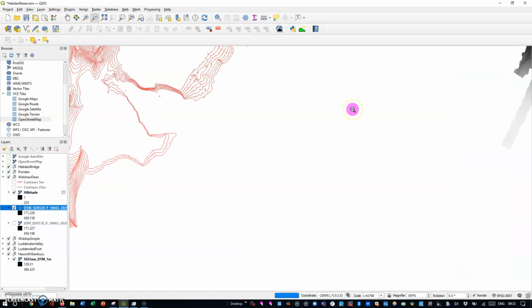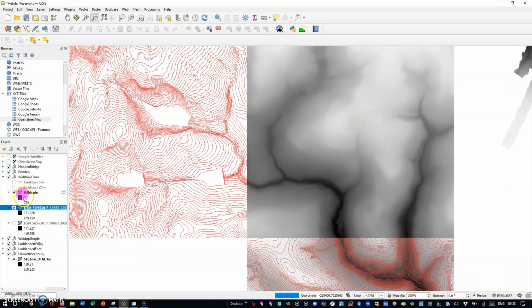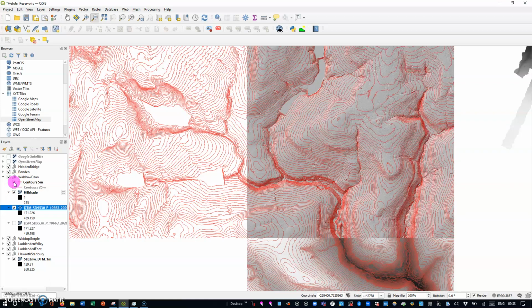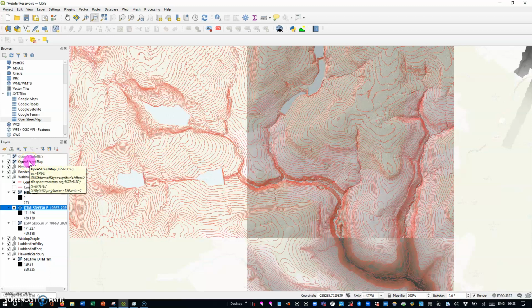We just go in to have a little look, and I've also created some contours at different intervals. They default to 10 meters, and I've made this one 5 meters, and you can see we've got that. I've also got a watered down, transparent 20% Open Street Maps layer, which I've got from here, and this puts a bit of colour. It puts a colour wash over the top. If you double click these layers, you get the properties.